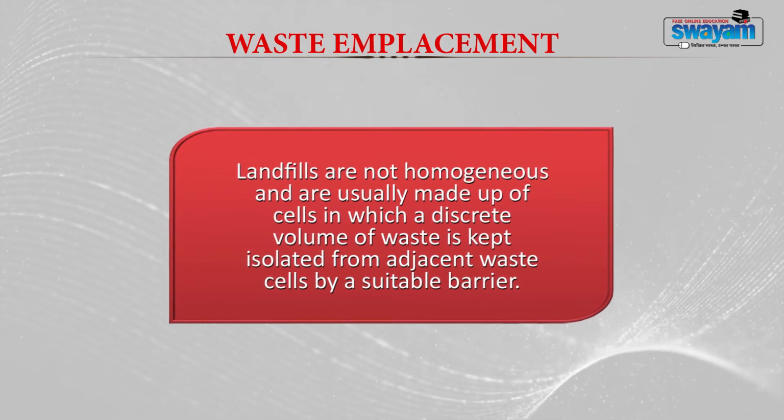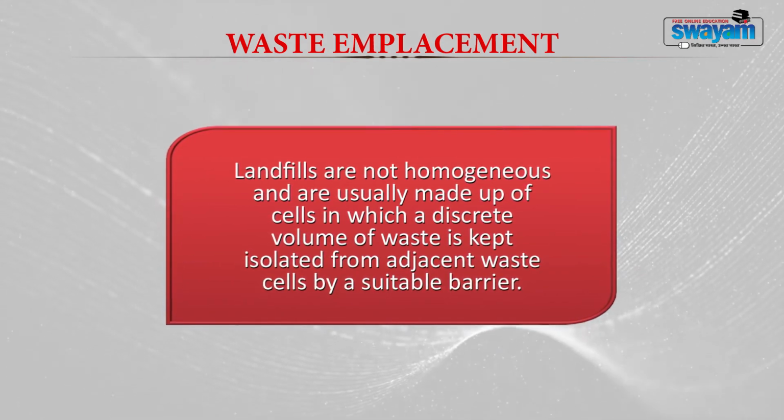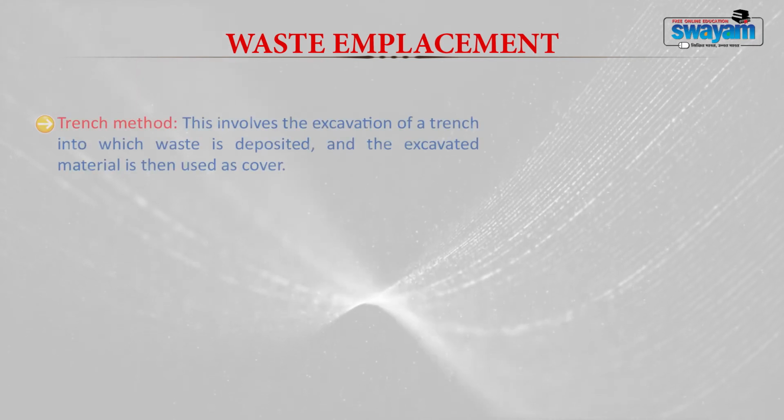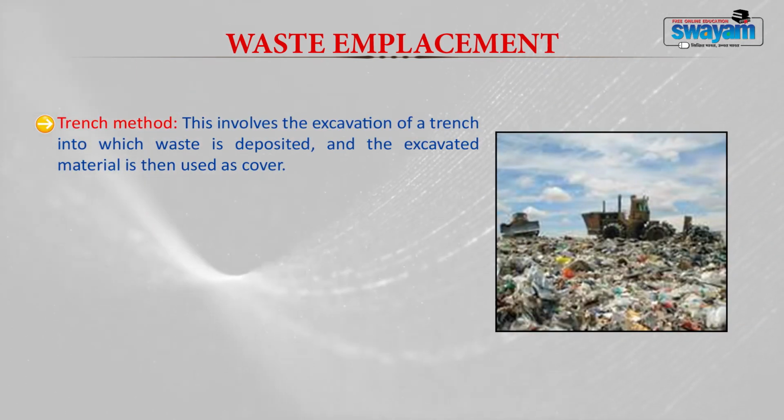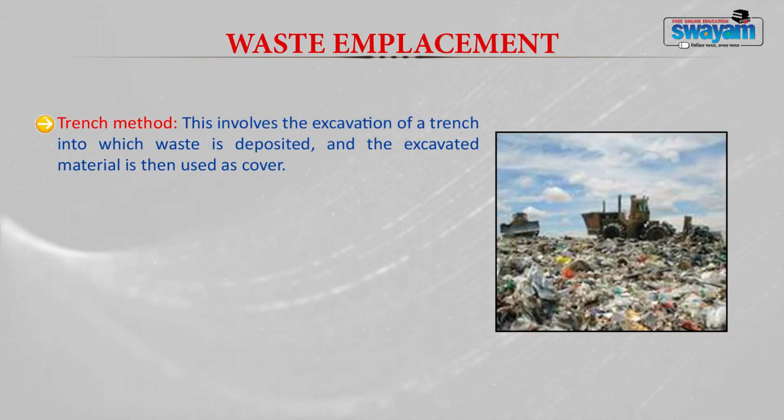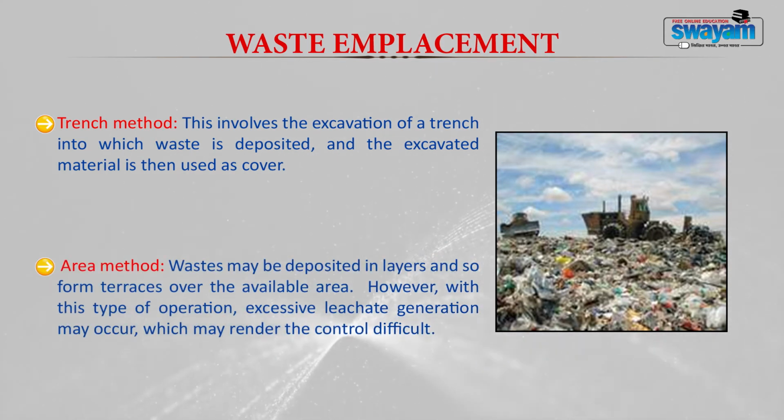There are different methods of waste loading in a landfill. The first one is a trench method. The trench method involves excavation of a trench into which the waste is deposited and the excavated material can then be used as a cover. The second method is an area method where the waste is deposited in layers.